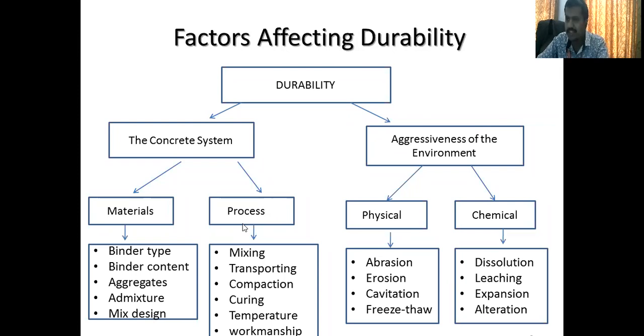Mineral means fly ash, surkhi, bagasse ash that you are using. Okay. And chemical admixtures, there are so many: air entraining agents, gas forming agents, plasticizers, super plasticizers, water reducing agents. Okay, these are chemical admixtures, some examples. I think you have gone through that part. So the admixtures that you are using. Okay, then mix design.